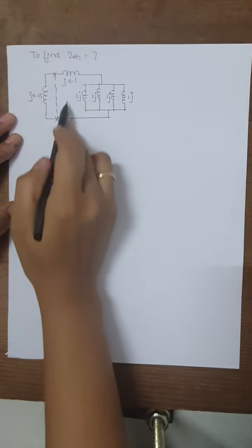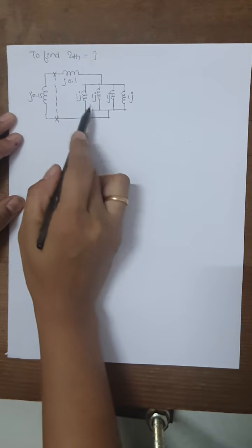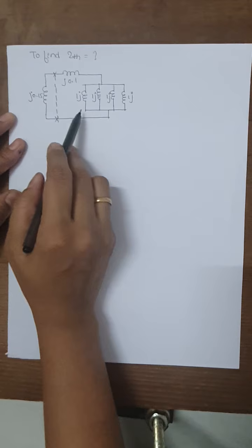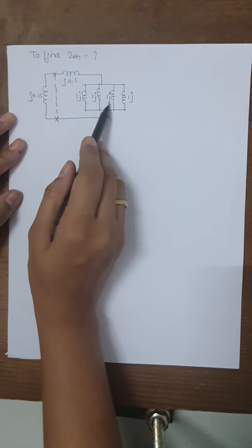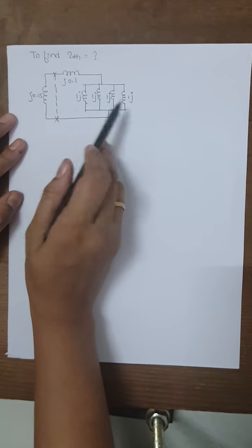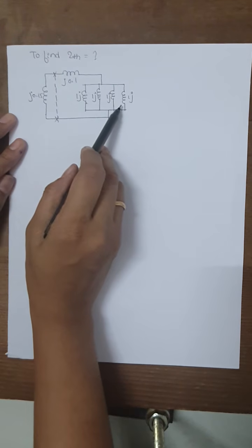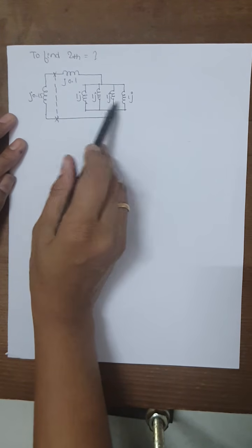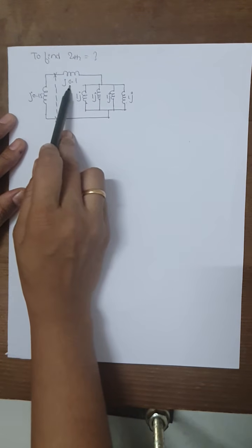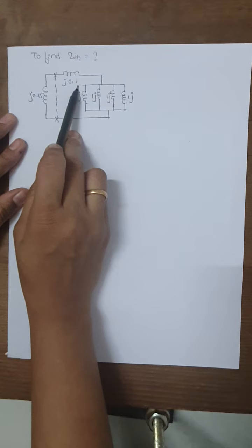For finding the ZTH, the same reactance diagram has been written this way, and here is the point where the fault has occurred. Here you need to observe that all the 4 motors are identical and connected in parallel. So we need to use the equivalent reactance for all these motors, and then add this equivalent reactance with the J0.1 reactance of the transformer.